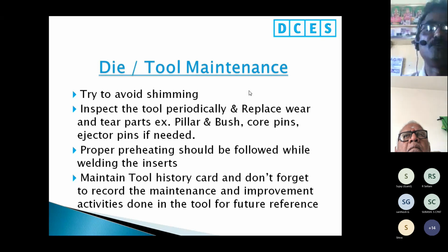Proper preheating should be followed while welding the inserts. If we want to go for welding the insert, proper preheating should be done. Maintain the tool history card, and don't forget to record the maintenance and improvement activities done on the tool for future reference. Sometimes people do maintenance every time, but they don't record it properly. It should happen.